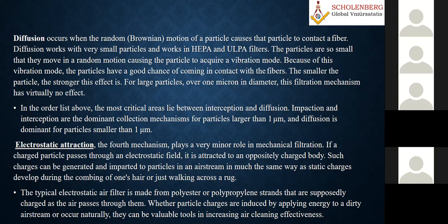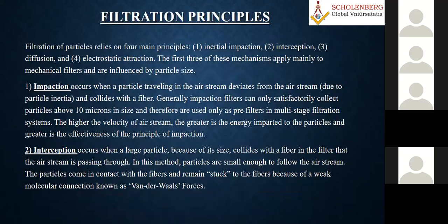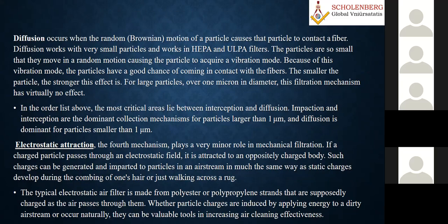So the smaller the particle, the stronger this effect. For a larger particle, over 1 micron in diameter, this filtration mechanism, diffusion, will definitely not work. I am trying to make you understand the processes: the first is impact, interception, and then diffusion. Then electrostatic attraction, the fourth mechanism. It plays a very minor role in mechanical filtration, because in mechanical filtration this will not be there.